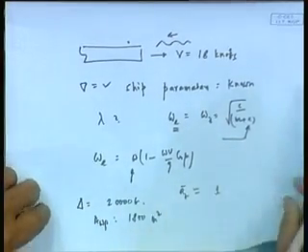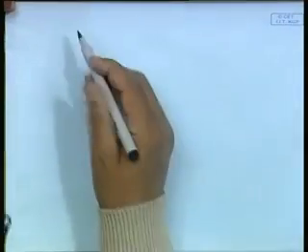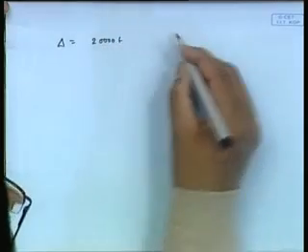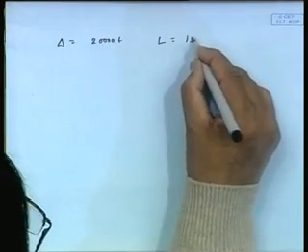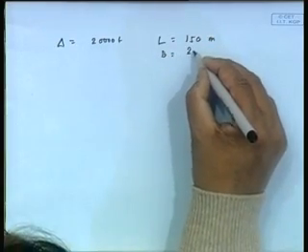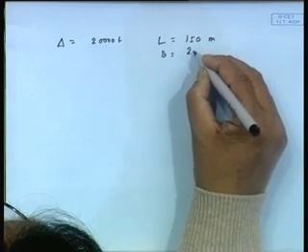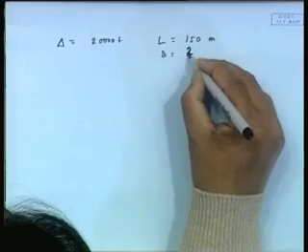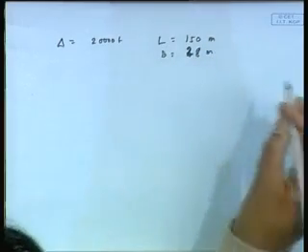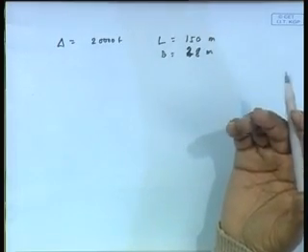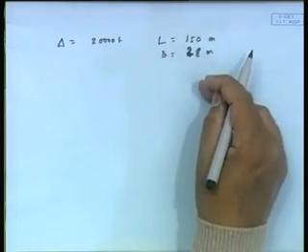So, let me organize this and write it properly. I have displacement of 20,000 ton. Actually, let me put it the other way around: L of say 150 meter, B of maybe 30 meter. No, let me make it 25 meter, because 30 makes L by B too short, 25 makes it L by B of 6, so 25 is a good number.